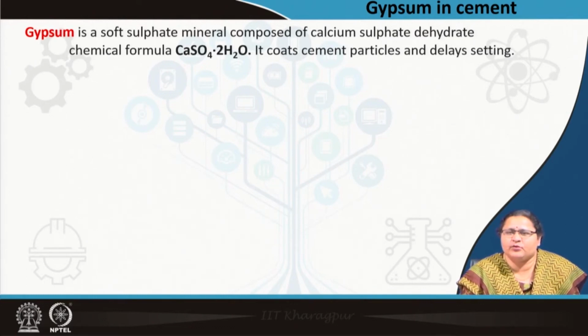Now, this clinker, what has happened? This clinker needs grinding. This clinker needs to be dry and cold. So, those are preserved, those are cooled, and now you are grinding it. When you are grinding, you are adding this gypsum to it.